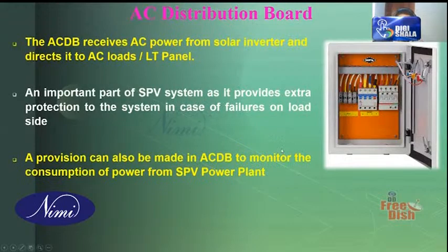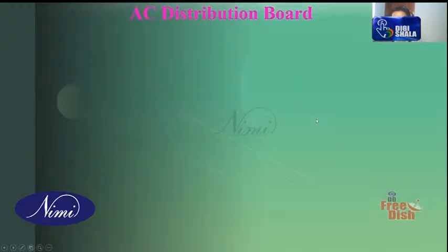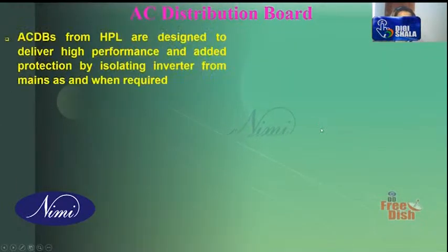And you can disconnect the inverter from the load when you switch this off. Of course, an isolator will be there. You can isolate here also. Maintenance will be very easy. You can maintain different systems separately. For repairing and maintenance, it will be easy.